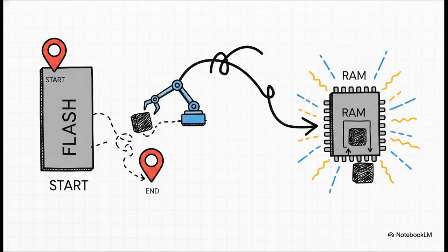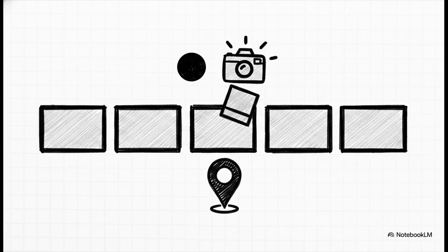Think of them as precise GPS coordinates. The bare metal reset handler uses these start and end markers to run a byte loop, copying the flash memory into RAM and effectively waking the hardware up. And you get to define those GPS coordinates right inside the linker script. See that dot symbol? That's a super important special variable called the location counter. As the linker goes through and sequentially places sections into memory, that dot tracks the current address. By using the PROVIDE command, your script dynamically grabs that exact memory address at that precise moment in the layout and assigns it to a symbol, like _etext.